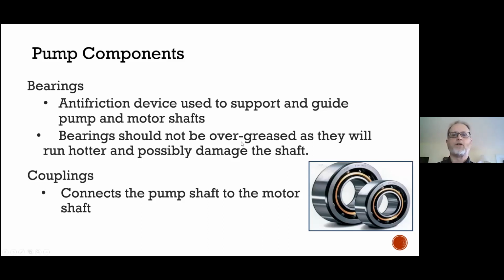Bearings should not be over-greased, so we have to follow our manufacturer's specifications on that. Otherwise, the bearings run hot. They can actually damage the shaft itself or scratch and score the shaft. The couplings, we saw a couple of examples of them. If it's a frame-mounted type of motor and pump assembly, there are 2 shafts. They need to be connected and then properly aligned.